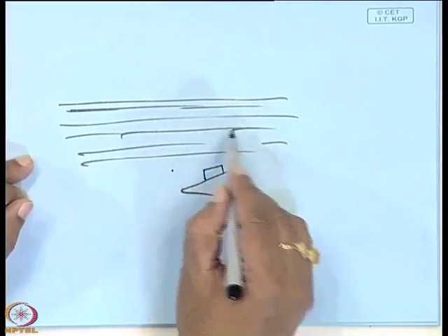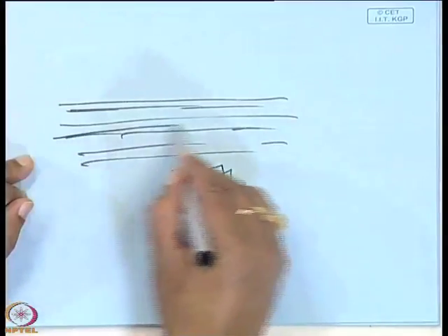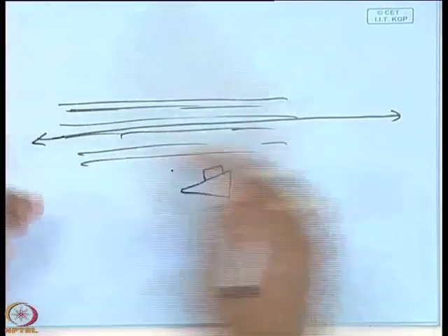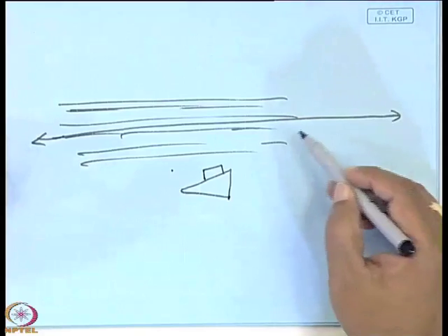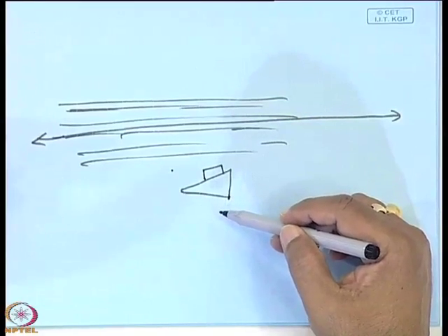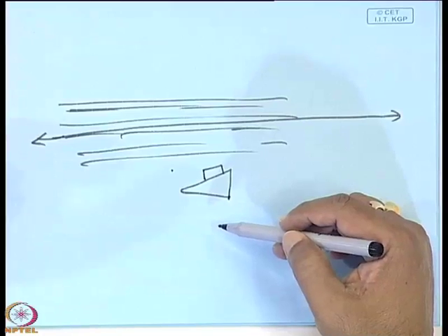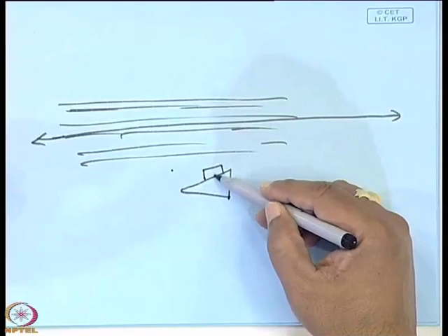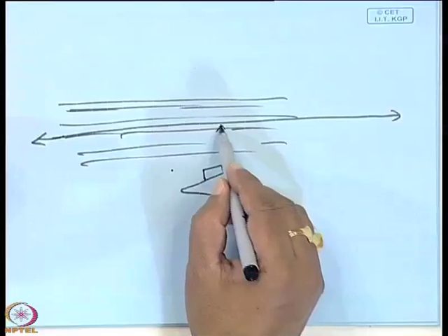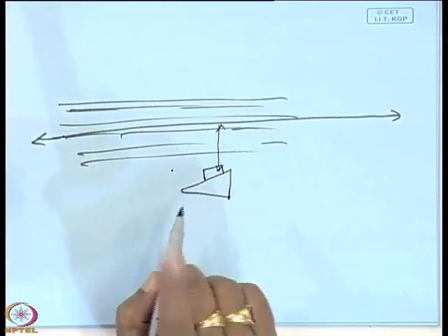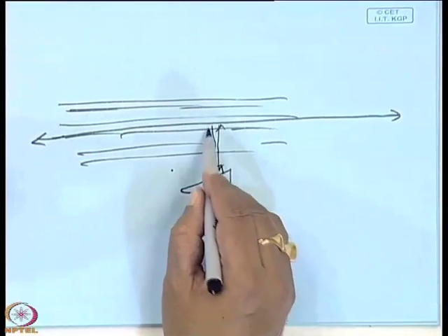This gas, you can say that this is a boundary layer. Boundary layer means below this layer there will be diffusion of the different chemicals onto the substrate, and there is temperature variation. So, our idea is that it must diffuse, because unless it is diffused from the main gas stream, there will be no reaction, because adsorption must be there, then decomposition, then some nucleation will be formed, and then the layer will be grown.